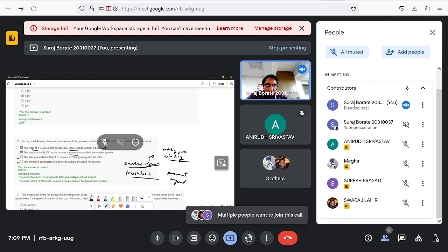It was asked for how much portion of the cycle, or the angular interval, the BLDC motor EMF will remain flat topped. If you look at this diagram that has been thoroughly discussed in the class, between 30 and 150 degrees you have 120 degrees, and then another 120 degrees, so it is 240 degrees. The key assumption here is that the rotor speed is constant.